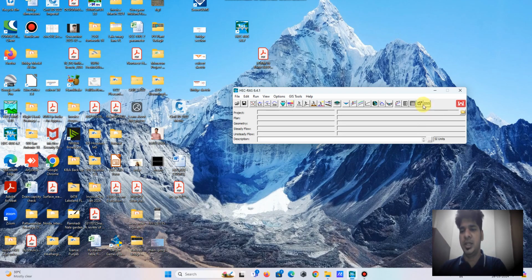Okay, that includes the table and the graph. So if you have the HEC package, that is the HEC-DSSVue, you can save the data and graph, and you can integrate this DSS data into other HEC packages like HEC-HMS or HEC-RAS to view the results.